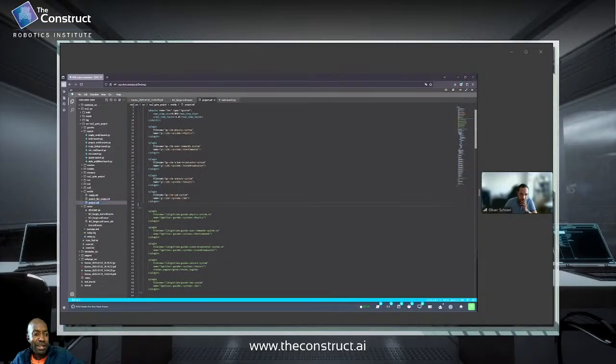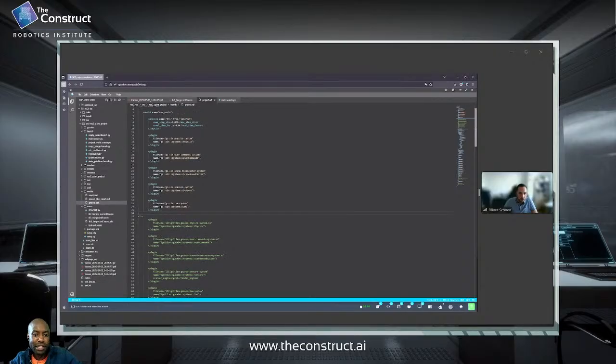The reason why we have sensor plugins in the world files is that's where the physics is actually happening, right? Whereas with Classic, this needed not to be done exactly. There was no strict rule that said we should have them there. So it works better in simulation in the world files, because then you don't have your simulations dependent on the robot itself. You just have the sensors in the world files, and when you change a robot, you don't have to change the sensor itself if it's the same sensor. So theoretically, I could just put a sensor in my simulation world and use it without having the robot, because I already have a plugin in my world file, so everything is already prepared. Yes, that's correct.